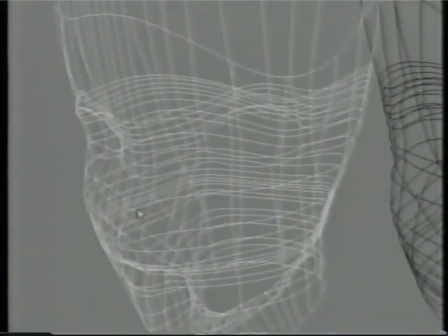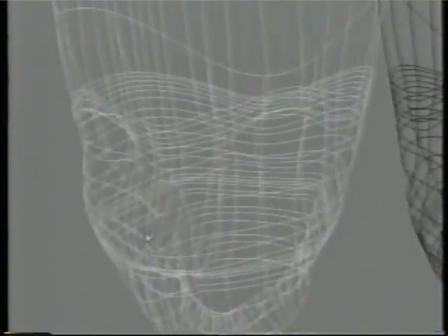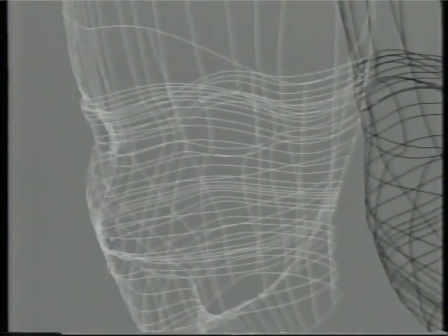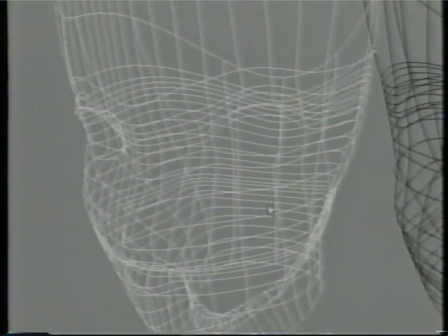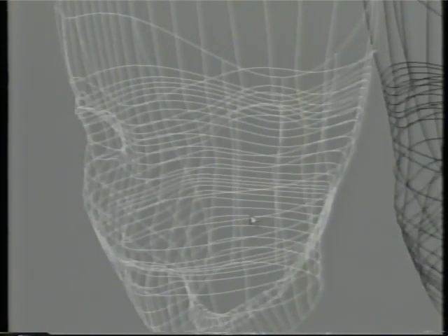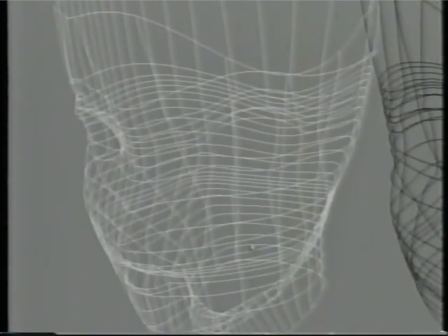And what's happening when you use the effect reparameterization feature is that the knots on the surface, these curves here, will actually travel along the other curve, and the distance between them is changed, and that affects everything from the shape to the texturing of the object. So let's look at that one more time. Go to chord length, it's the same. Go to uniform. So you can see that the overall shape stays about the same, but there are small changes. But there are pretty major changes in the positioning of the knots within the surface.